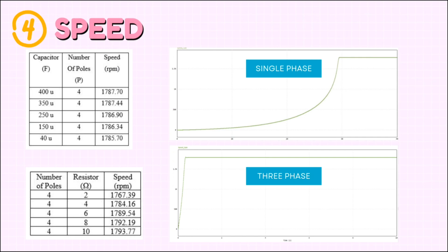The speed of three-phase induction motor is slightly higher than single-phase induction motor. The speed of induction motor for three-phase is changed from both stator and rotor side. Speed control methods of induction motor can be done by changing the number of stator poles. This method is generally used for squirrel cage induction motors, as squirrel cage rotor adapts itself for any number of stator poles. Additionally, the speed controls of three-phase induction motor from rotor side are further classified as adding external resistance on rotor sides. This explanation is for three-phase induction motor.